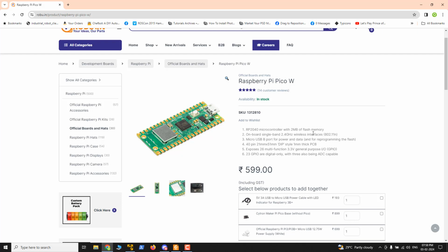Okay, the main thing about ROS serial is that it's a serial communication based protocol, so it will not take much CPU or RAM. But micro ROS is not like that. With micro ROS we can run a micro version of ROS 2 inside the microcontroller. So if you take the old Arduino Mega or Arduino Uno, it does not have the resources to run micro ROS.